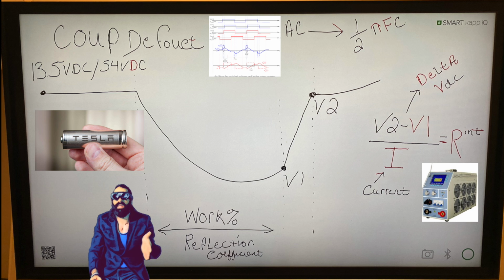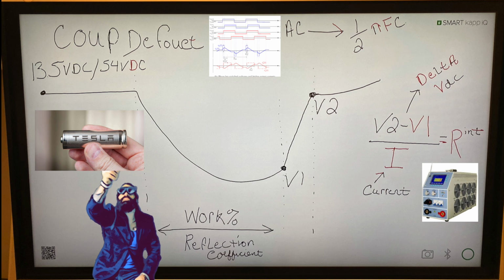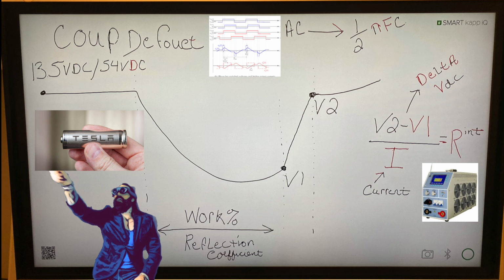The DC bank is outputting DC current into the inverter. Why would you test a battery system with an AC signal source, AC impedance, an AC voltage, or an AC current? And there's a lot of problems inherently in testing bigger battery systems with AC signals. Number one, you have capacitive reactance. I think there's a formula, 1 over 2 pi times F times C, where F is the frequency of the testing device, and C is the capacitance of the battery, right?